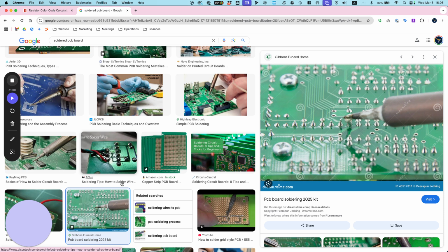Wow, this thing is mostly what? Mostly charged. I would say it's basically like 95% charged, okay? All right. I will go more into battery care, but this is actually not a good thing, to keep it fully charged. Lithium-ion batteries like to be kept at like a 60% storage mark, since this has been sitting here since last semester.